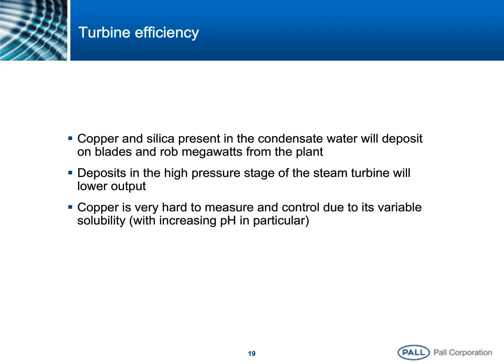Copper is a special challenge in water because it's quite hard to measure and control. Its solubility range is right in the range of pH, temperature, and pressure that we're dealing with usually, so that copper tends to go in and out of solution. Sometimes it's particles that you could hope to be removing. Sometimes it's dissolved back in the water and all the way making its way through the turbine. So it's a specific challenge.